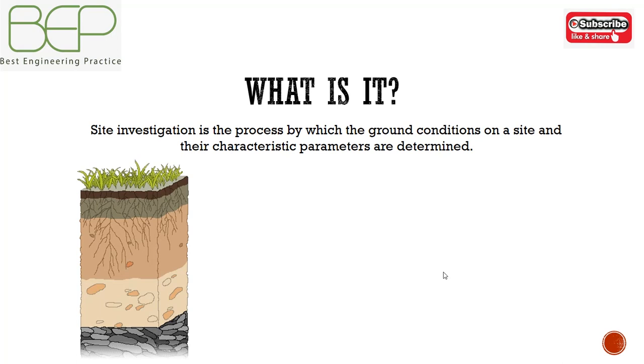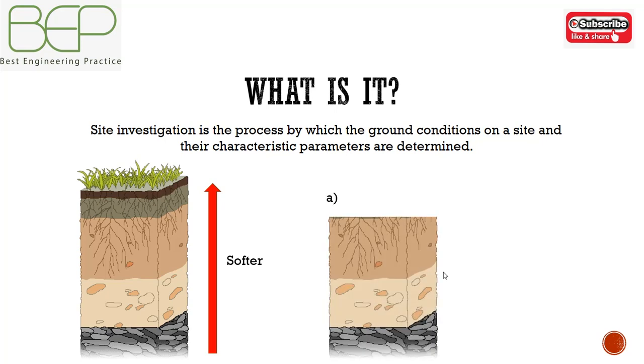Near surface soils tend to be softer, weaker and more variable than deep soil, and they therefore may require more extensive and more refined methods of site investigation than deep foundations. If the contractor is free to build a retaining structure by any method, then for example, he might place the structure with a minimum of disturbance to existing soil.